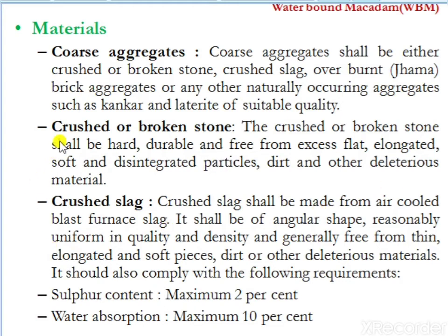So next material, crushed or broken stones. The crushed or broken stone shall be hard, durable, and free from excess flat, elongated, soft, and disintegrated particles, dirt, and other deleterious materials. So the crushed stones or broken stones, which are used in the construction of waterbound macadam pavement, should be hard.